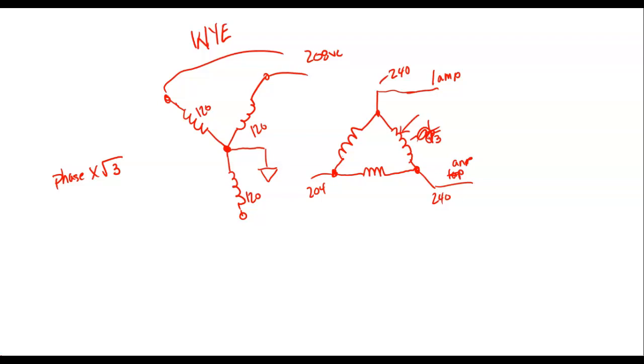So the advantage of a Y transformer is we get 2 voltages, we get a high and low voltage out of it. The advantage of a delta is that the transformers only have to provide 1.7 less than the actual line current. Motors makes absolutely no difference right now.